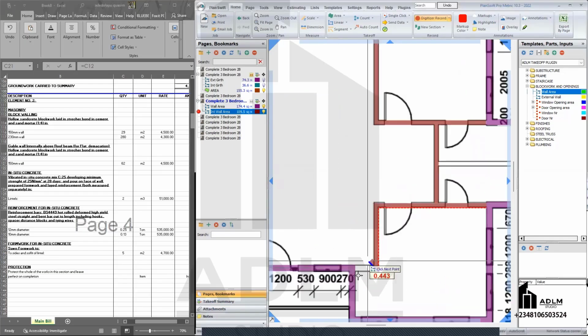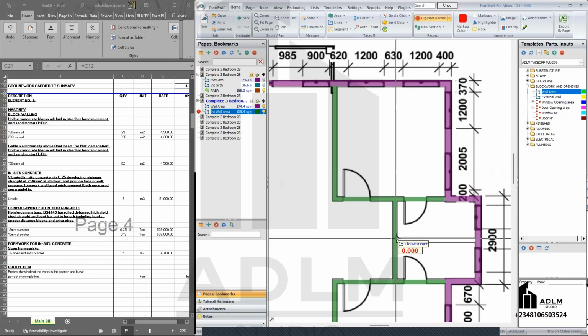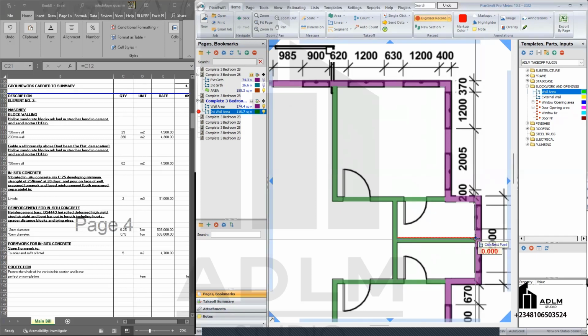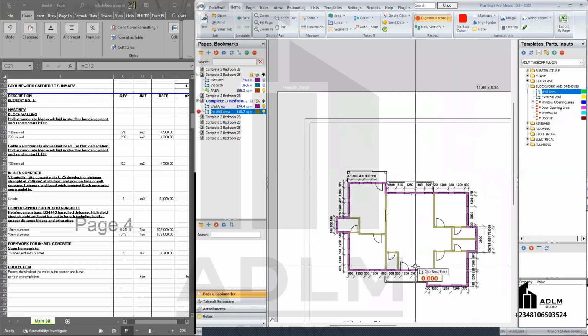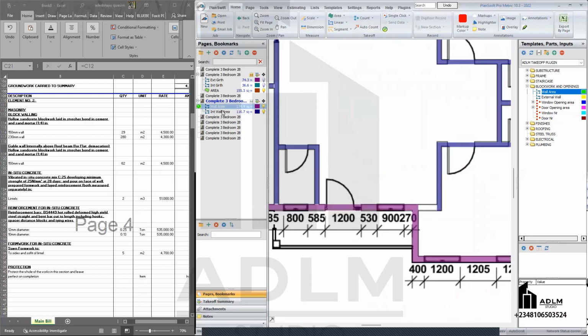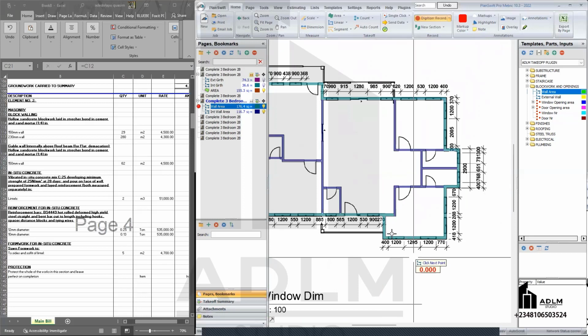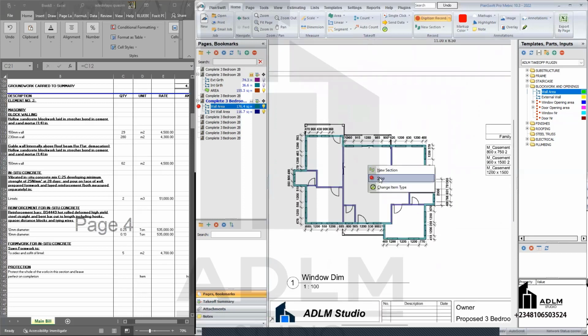Now this is for 230, so I'll just terminate this here by double click. That's left click twice. You can see I picked up my 150 walls already. If I click stop. Now for 230, I'll just come back here. See what area, just turn this back on here and just pick from here to here. And now we are good. So I've picked for all of my walls, right?